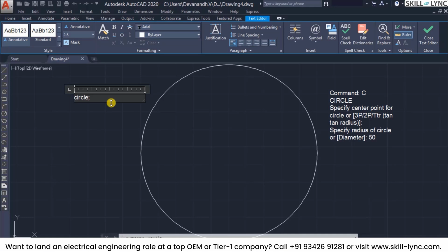If you can recollect in the macro action tab, we had given a symbol for passing to take in the user input. Because the next command is we need to specify the center point as the default. Towards that, we need to execute this slash command. That will tell AutoCAD to pause for a user input. Once that's done, it goes for the next input.